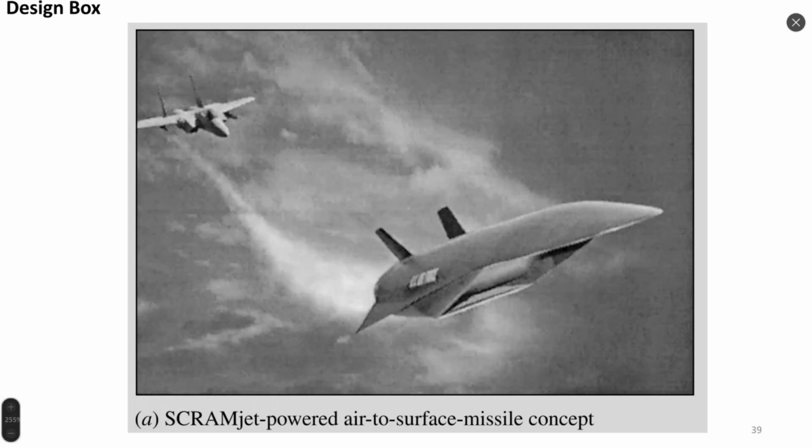Since such flow is reversible, you can calculate not just from Mach 1 to Mach 2, but you can also calculate from Mach 2 to Mach 1, so calculate backwards. Sometimes it's interesting because it tells us which conditions we must create initially to obtain one or another value of Mach number, or specific values of temperature and pressure. Just by calculating Prandtl-Meyer flow backwards, you can answer those questions, because Prandtl-Meyer flow is reversible and can be calculated in both ways.